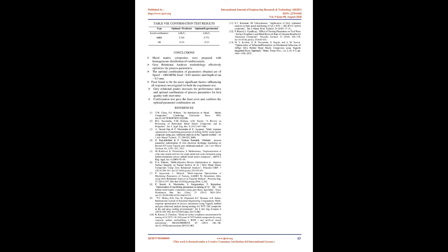It is observed that the feed, 99.90%, is the most significant factor followed by speed, 0.05%, and depth of cut, 0.03%. Fig. 4 Optimal process parameters.